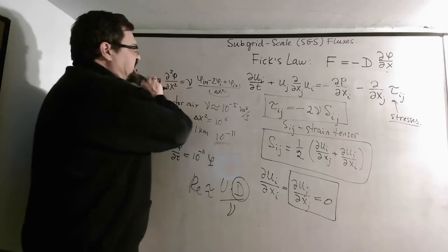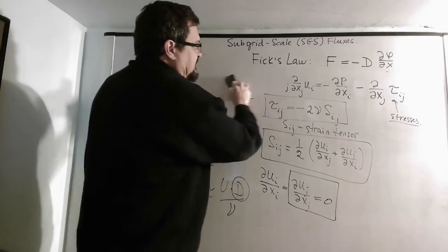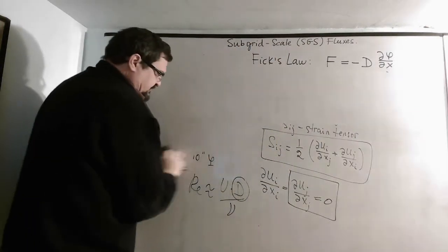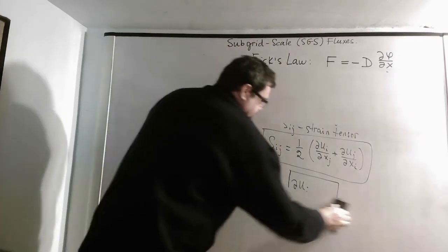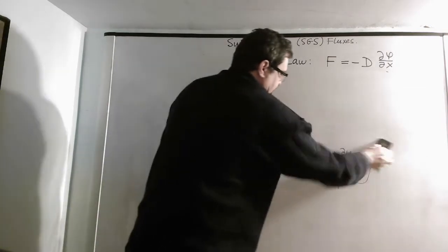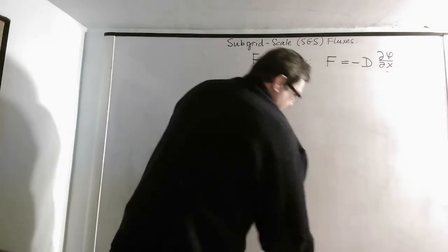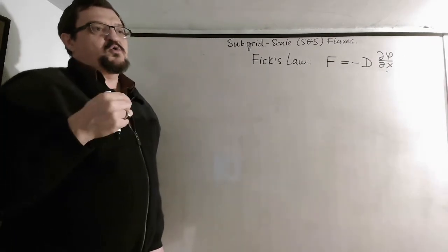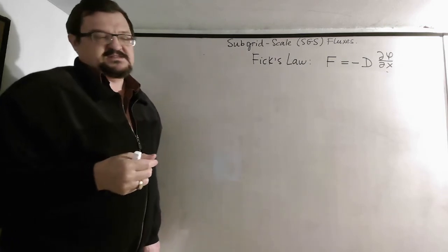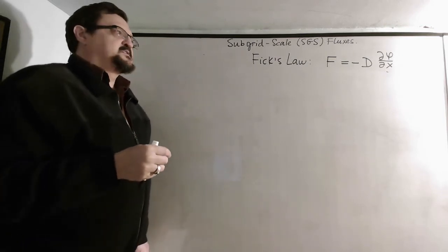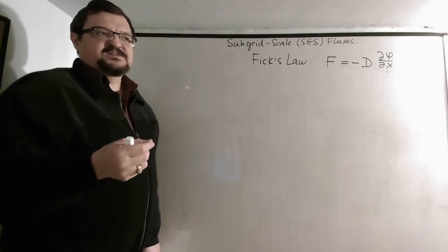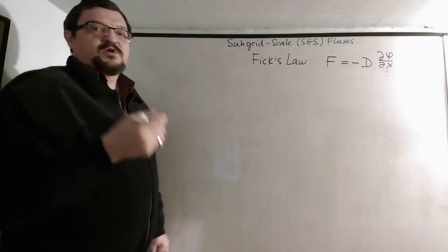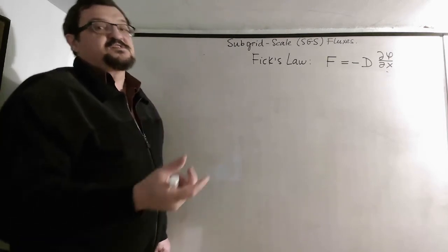So now, as we introduce this kind of convention and our primary laws that describe diffusion of momentum and scalars, let's talk about turbulence. We established that our Reynolds number for the atmosphere is very large, so our flow is almost always turbulent to various degrees. So we need to describe this somehow. We cannot describe it by molecular diffusion anymore.